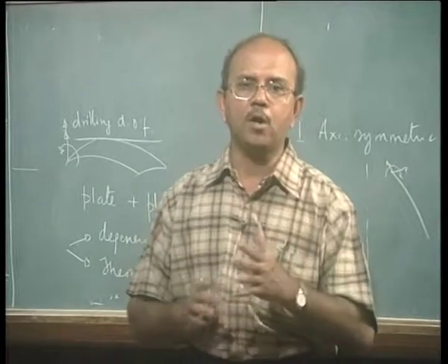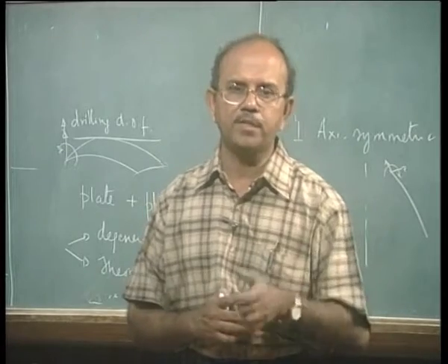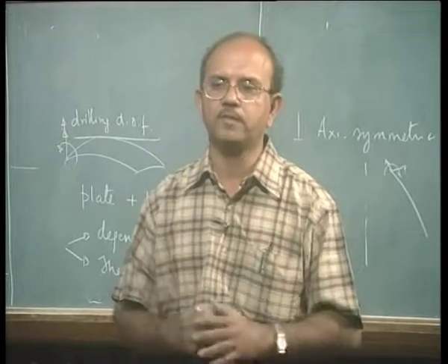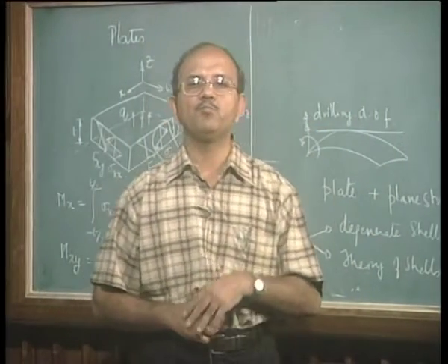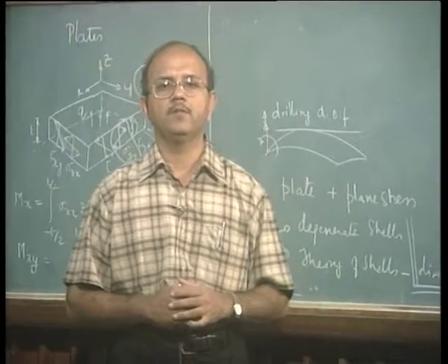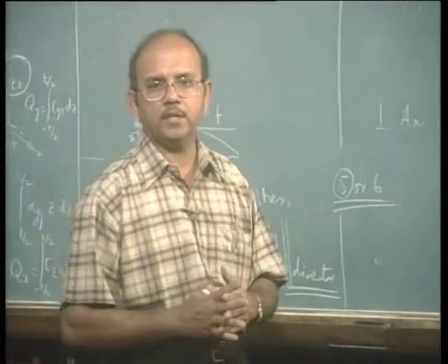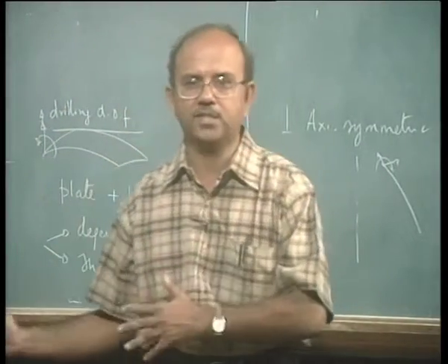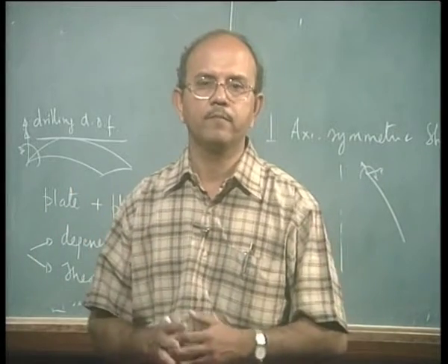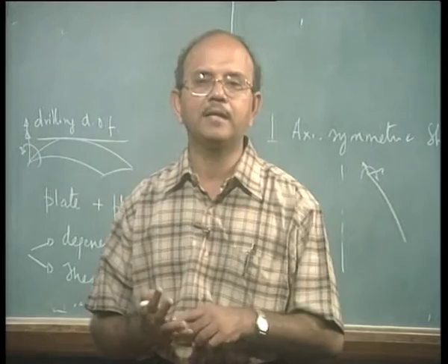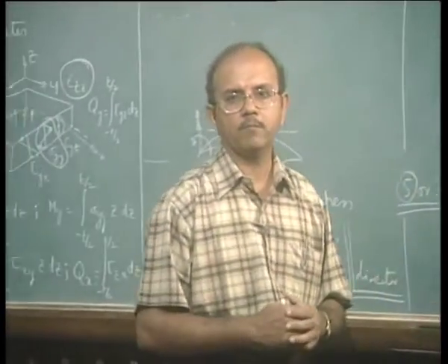In the process of dividing into a number of nodes and elements, we realized that not only geometry is important, but the structural behavior is important. From that point of view, we had a number of elements to mimic the structural behavior. We said that the structural behavior can be looked at as plane stress, plane strain, axisymmetric, plates and shells, beams, axisymmetric shell, and so on. A number of them. Depending upon the structural behavior, we would choose an element and put it in place.